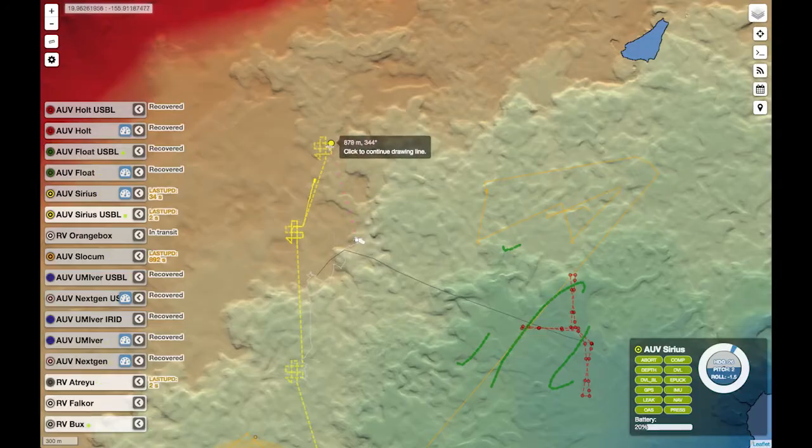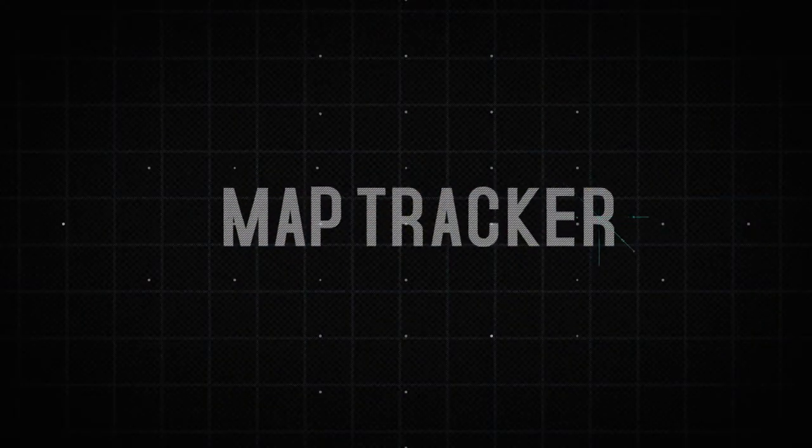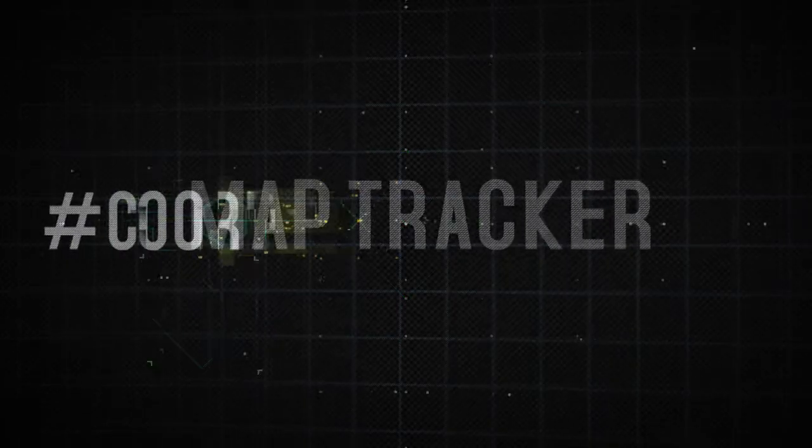So there's various hazards of having other vessels that aren't related to our research and that don't necessarily know that we've got AUVs in the water operating in the area, and that poses a hazard to the robots. And so the ones that have AIS transmitters, we can actually track through the MapTracker as well. We've integrated that data stream so we can see where those ships are and what velocity and direction they're heading in, and we can plan around that as well.